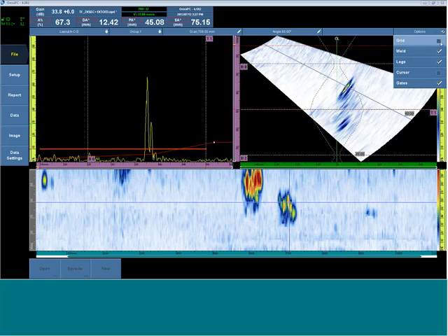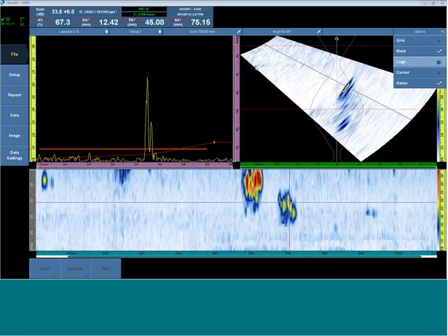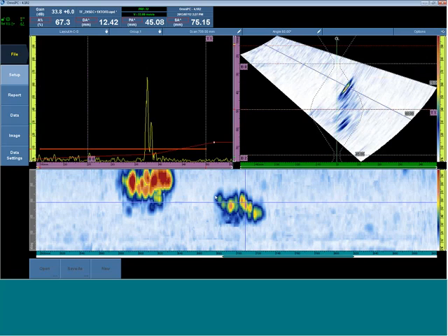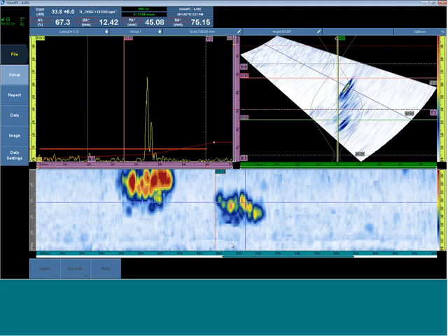So my length sizing was done on the C-scan. I can zoom right away without any touchscreen mode. I can place the cursors quickly and easily on the data. And by right-click or touch and hold on the touchscreen, I can add the indication to my indication table immediately. All of this directly in either normal screen or full screen mode.